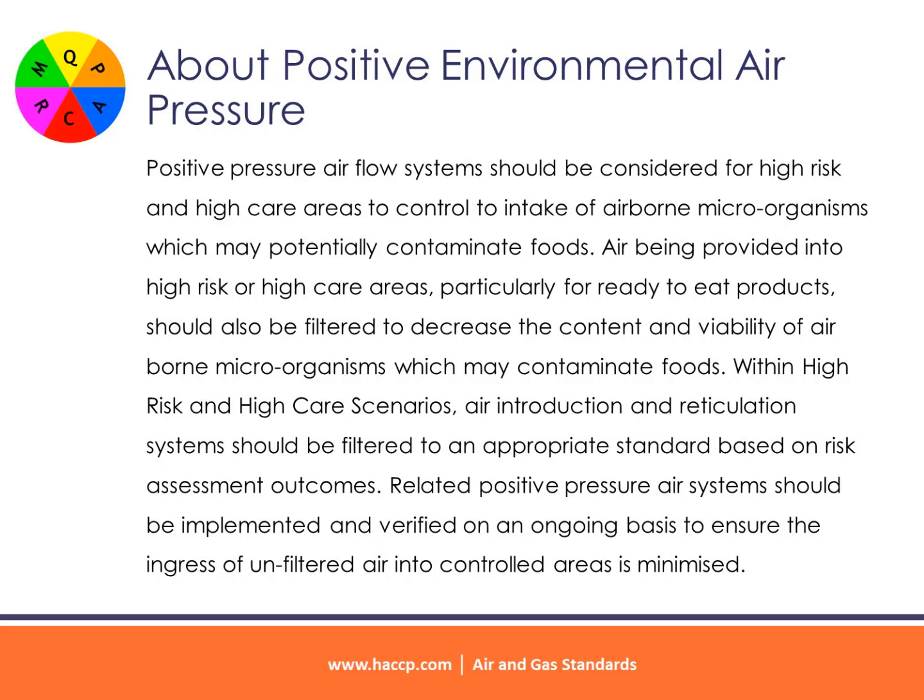Within high-risk and high-care scenarios, air introduction and reticulation systems should be filtered to an appropriate standard based on risk assessment outcomes. Related positive pressure air systems should be implemented and verified on an ongoing basis to ensure the ingress of unfiltered air into controlled areas is minimized.